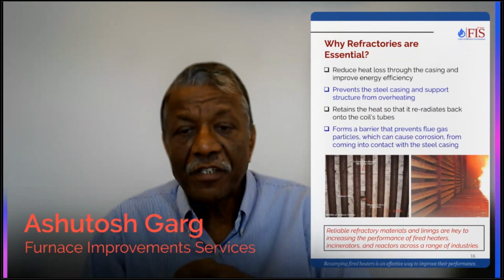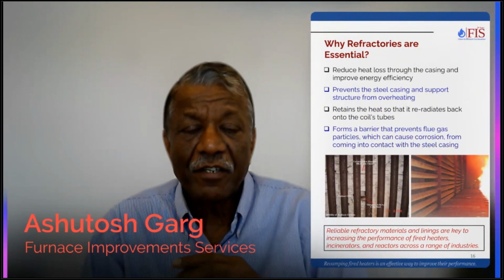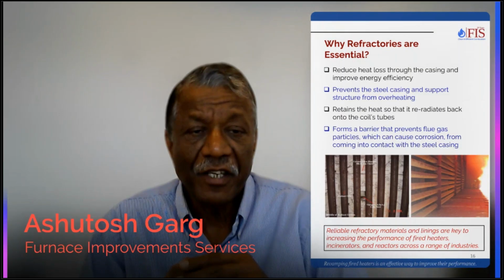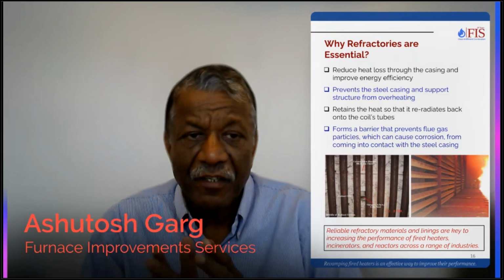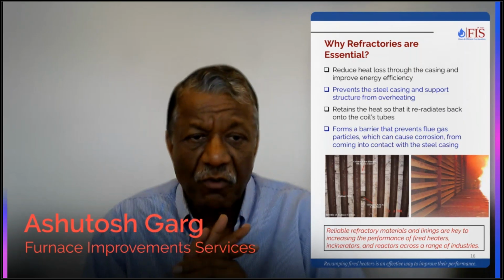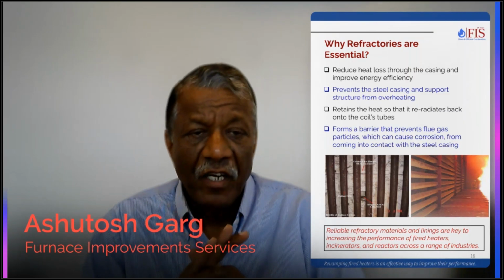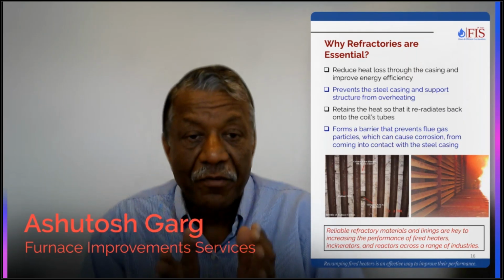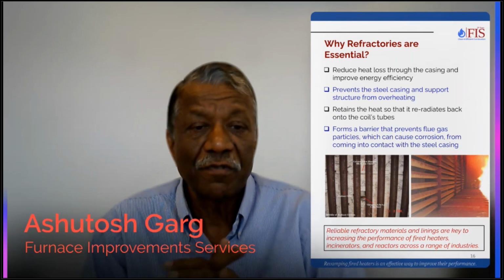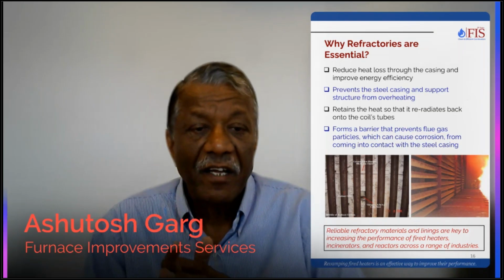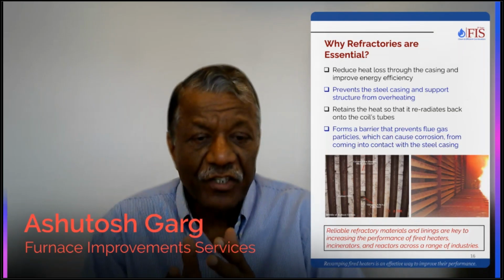So what is the need for refractory? Reduce heat losses through casing and improve energy efficiency. Prevent steel casing and substructure from overheating. It's basically absorbing the heat and then radiating it back to the tubes. So that's basically the three functions of refractory.